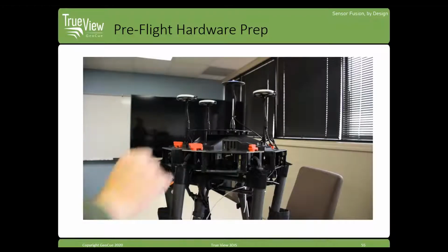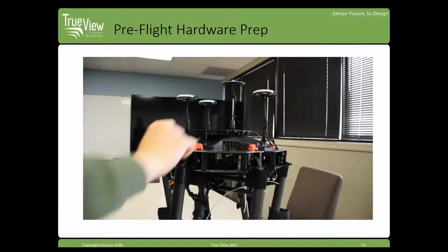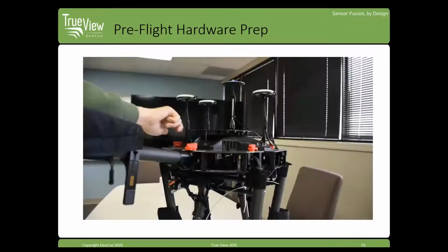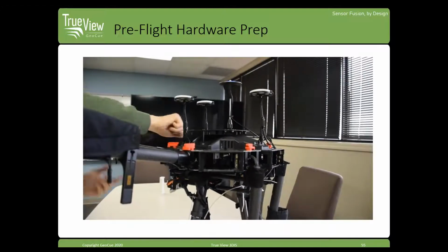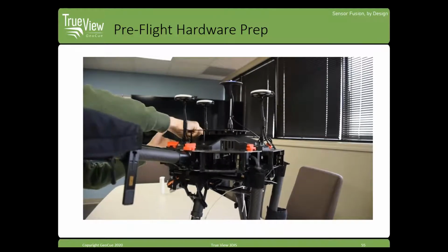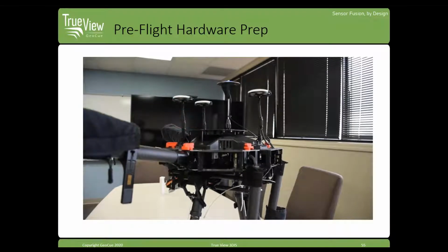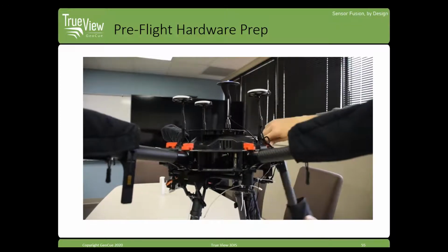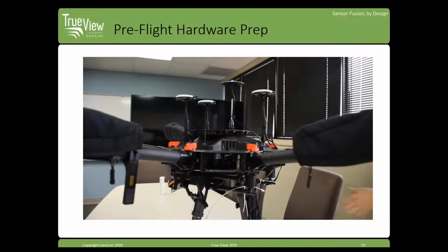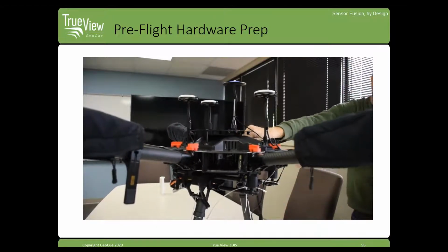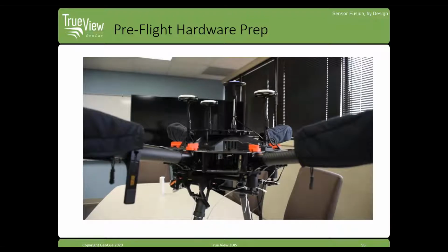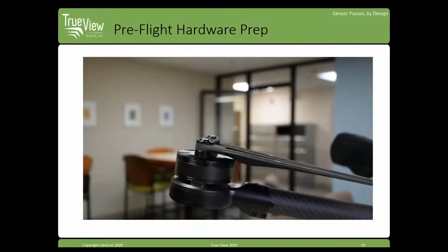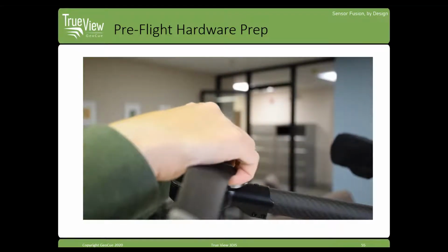And we'll be adding more videos, especially with the M300 as we get them. We're working on those now. Next, you'll want to fold out the arms, all 6 of them for this aircraft. Next up, just pull off the prop protectors and fold out all the props.